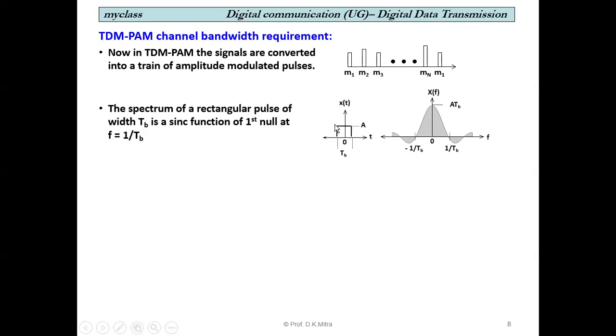If you take the Fourier spectrum of this, it becomes a sinc pulse, and the x-axis becomes the frequency axis, and the y-axis becomes the amplitude of that particular frequency component. Sinc pulse, if you remember, in communication engineering, we consider the sinc pulse as sin(pi x) by pi x, whereas sin x by x we call the sampling pulse. Anyway, so you see, this Fourier transform is infinite.